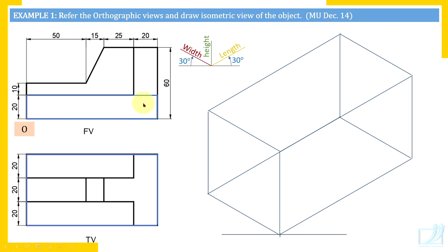On this base plate there is a rectangular plate. Watch here, this strip of thickness 20 millimeters. And this rectangular strip matches with this rectangular surface. Now since there is no dark line here, this rectangular surface and this rectangular surface, that is this T-shaped surface, is a single surface. There is no change of surface. That is because this surface and this surface here, these top surfaces are in one plane.